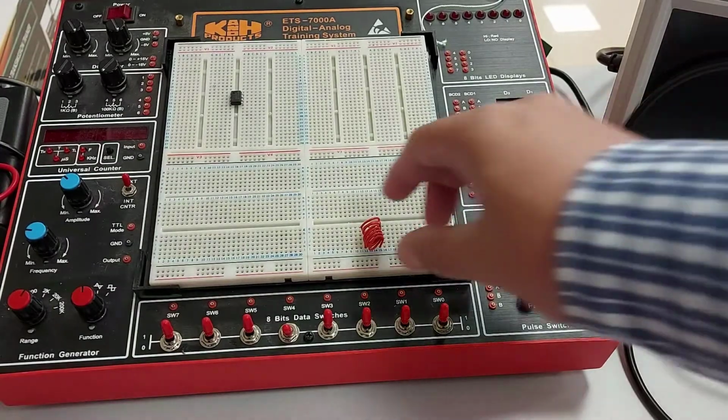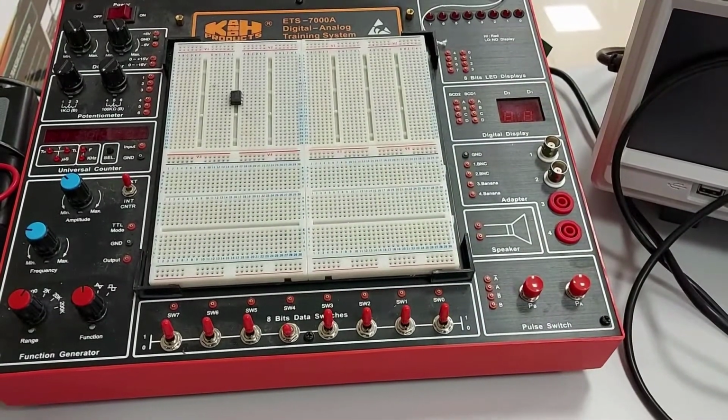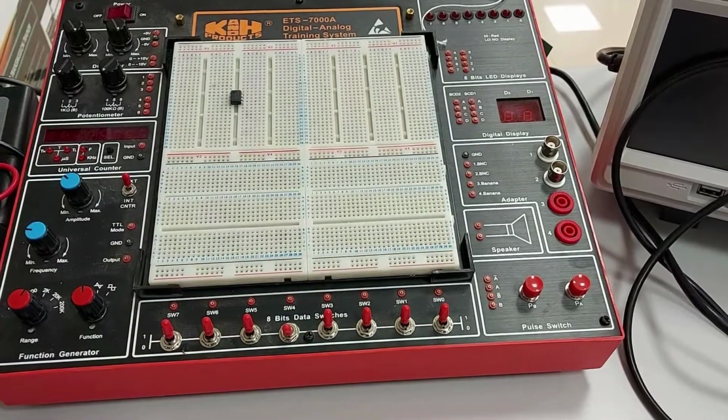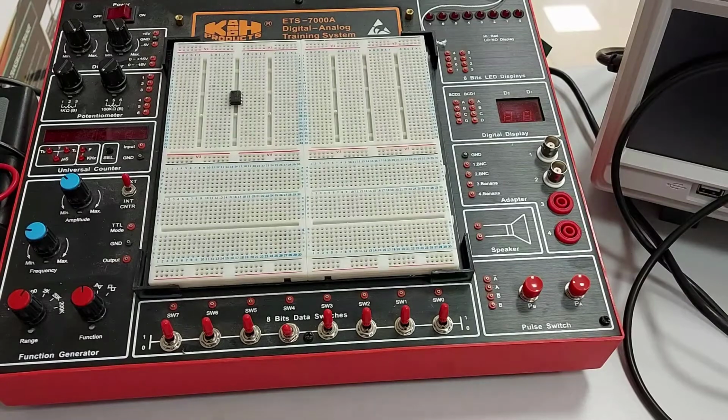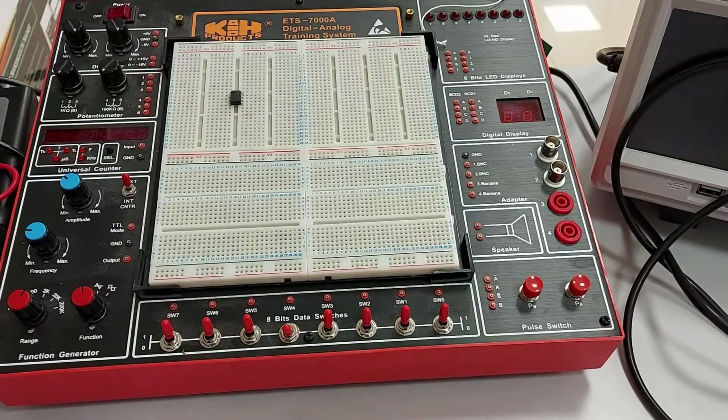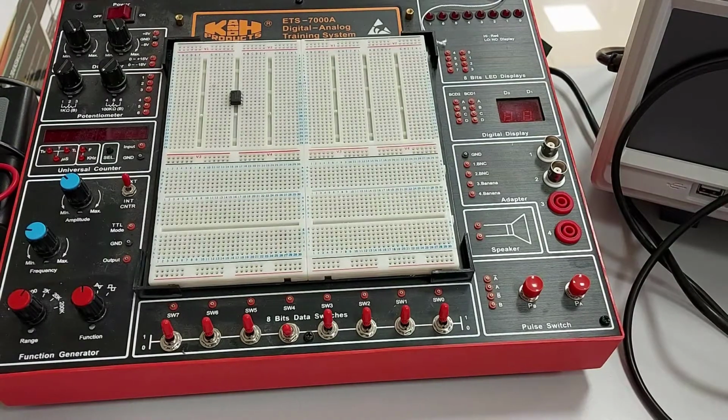So once you have all the necessary components, then we will connect the circuit for circuit number 1, the low pass filter of first order Sallen-Key. There's a question here: calculate a low pass filter of first order Sallen-Key with gain equal to 5 and cutoff frequency 3000 hertz. Assume the capacitor is 10 nanofarad and R1 is 10 kilo ohm. Then plot the frequency response of this low pass filter.